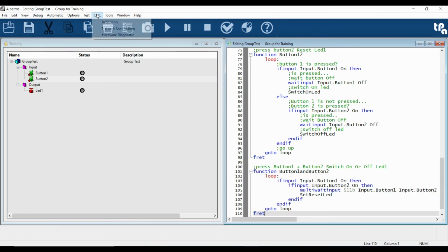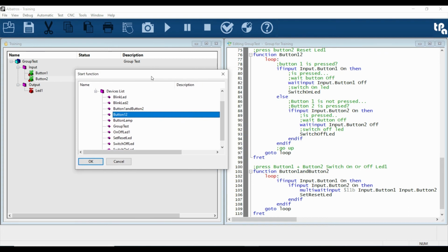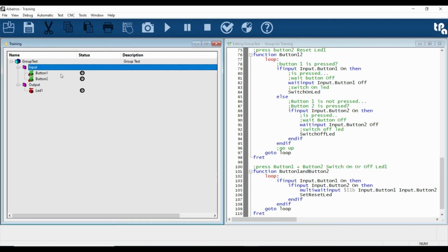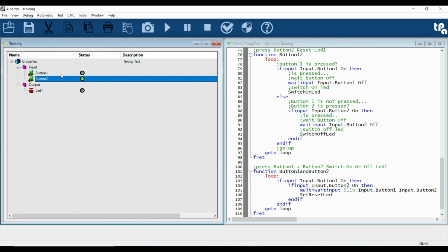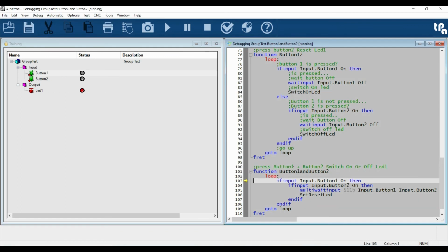All we have to do is saving, initializing, and testing our new function. First thing, we'll check that by pressing and releasing the single buttons, not at the same time, the output doesn't change its status. Now, we'll check that, instead, by pressing and releasing them at the same time, firstly by forcing both the inputs on and then by forcing them both on-off.